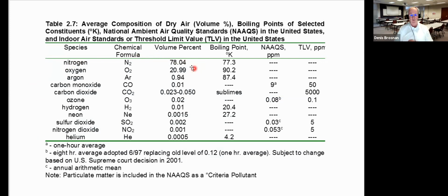Now, in some ways, nitrogen goes along for the ride in combustion, and we're going to have to supply energy to heat it up because it's going to be present in our kiln atmosphere. It's not going to be useful to us, although at very high temperatures we can oxidize it. So oxygen is there to create the work of firing when we're using air as an oxidant.